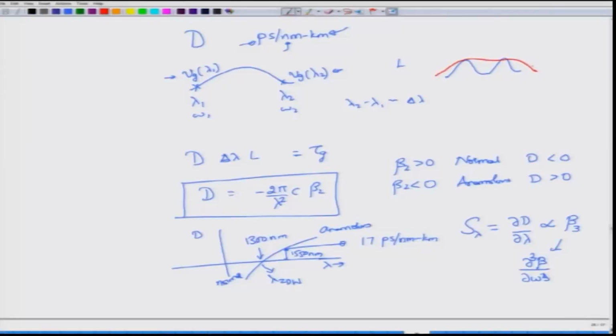So, if you actually send in two pulses, then both pulses essentially broaden out and then kind of overlap. So, this is what you would get at the output, while this is what you have sent at the input. So, you can't really distinguish one pulse from another pulse, and if you send it through an eye diagram, you will see that the eye diagram would be completely closed. So, you do not really see the system out there because of what is called inter-symbol interference. This interfering of one pulse with another pulse because of the broadening is called inter-symbol interference, and that is the major effect of dispersion in communication systems.